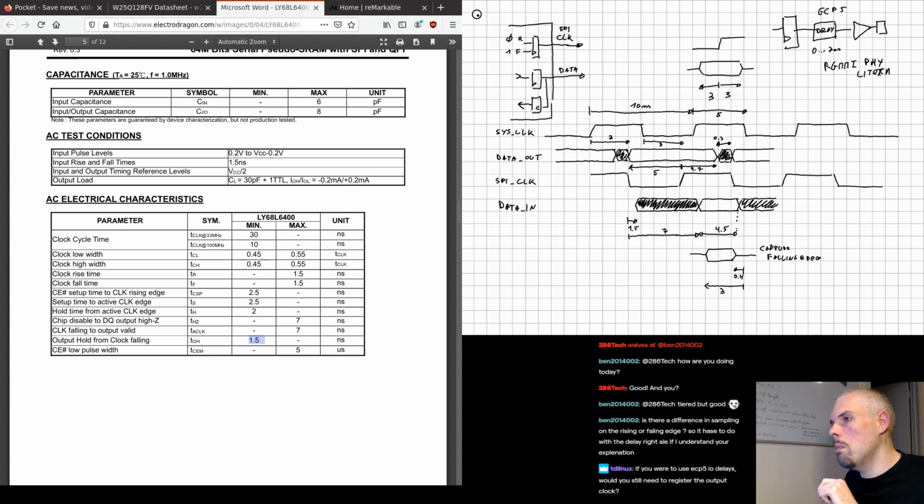So there is a dedicated path to input a clock. They also had a dedicated path to output a clock, which provided a known phase relationship. Now, that known phase relationship wasn't the same as the one if you used an I/O register, right? It would have been a different phase, which you would need to analyze using the tool.